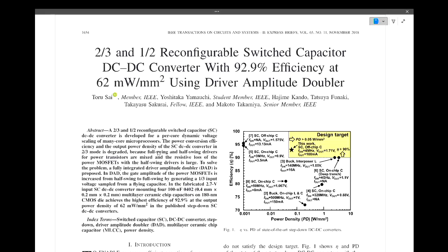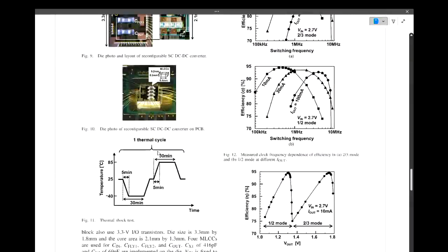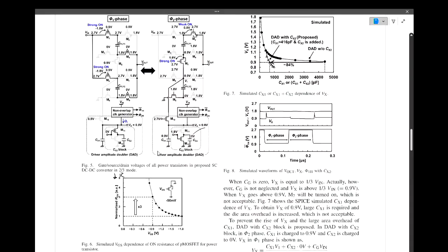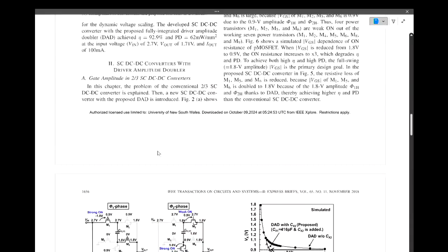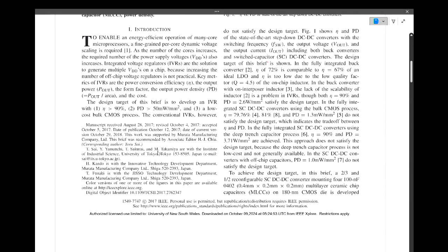So I think it's first. This must be charged up until full first before this one works. So in clock phase 2, both of these are connected to ground, so it's discharged. Yes, you start. And then during clock phase 1, you connect one to virtual ground and the other to the input voltage, so you charge it up to the input voltage.